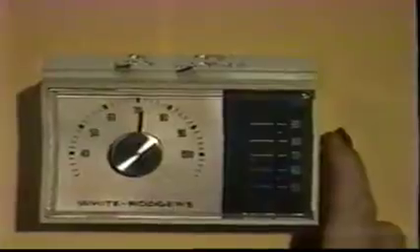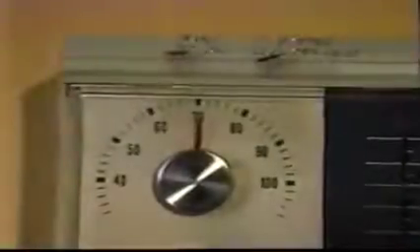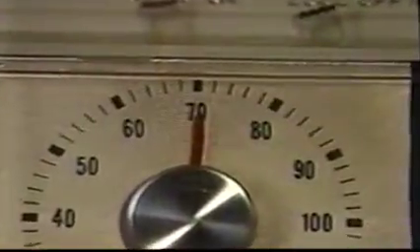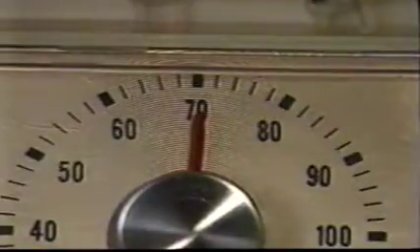Controlling temperature is not a difficult thing to do. Whether we are controlling a room or a fixture, the procedure is the same. Set the temperature we wish to maintain, measure the actual temperature, and cycle the equipment to bring about the needed change. The equipment remains on until the desired temperature is achieved, and then is shut off. This on-off cycling continues, maintaining a temperature very close to the set point temperature. Control systems work with this simplicity in millions of applications.